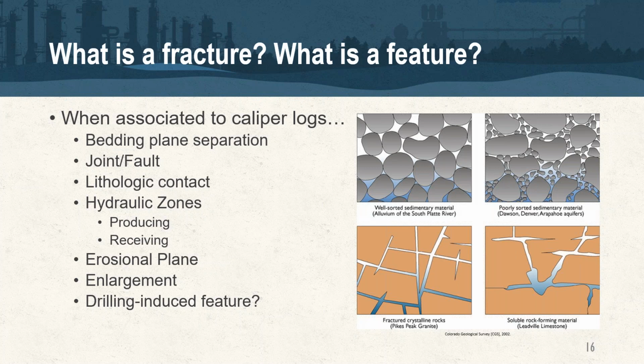erosional plays or enlargements from dissolution or whatnot, and then even potentially features that show a weakness in the geology during drilling. And what we want to be also careful of here is when looking at these, some of these features we may want to interrogate a little bit more later on down the line, or some of the other tools that we have that may not look like they're truly groundwater producing, but with developing those particular features, we may be able to find that they actually are key players within the groundwater chemistry that we're seeing within that borehole. And we'll talk more about that and why the injection tooling is critical for success in these particular applications when we go into our webinar next week. Next slide, please.